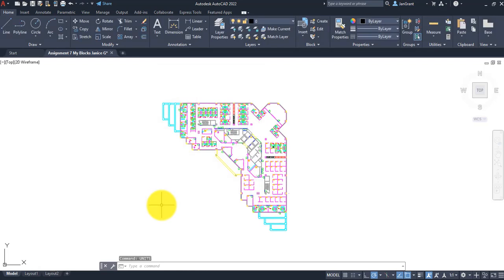That's it. Now, when we draw this rectangle, we'll be able to type in 2'6" for 2'6", or 5' for 5 feet. So you don't need to type in the dash or the inches. In fact, in AutoCAD, you don't have to ever type in the inches when you're drawing. The units don't change the dimensions either, so let's keep that in mind. It changes the way that you see it in the command line and the way that you can type it in. So we're drawing a rectangle.